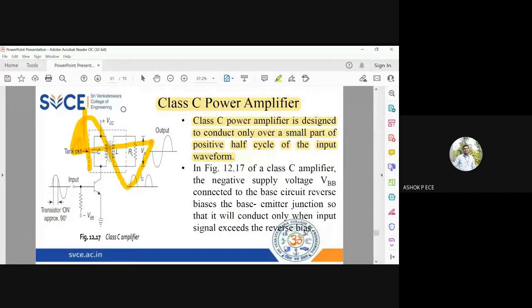50% I'm going to make the transistor work. It depends on my circuit. You have 4 portions, right? If you divide into 50%, you have 4 portions. So my transistor will be working in one among the 4 portions depending on whatever biasing I'm going to provide. Mostly it will be working in the first case, first shaded portion only. So only in the positive half cycle is my transistor going to work.